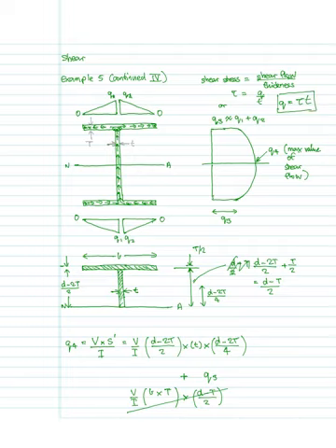So that shows the distribution of shear flow through the section, and then to turn that into the shear stress, you would then divide that by the thickness of whichever member you're considering. So for the flange, you would divide it by small t. Sorry, for the web you would divide it by small t, and then for the flange you would divide it by big T to give the value of the shear stress.